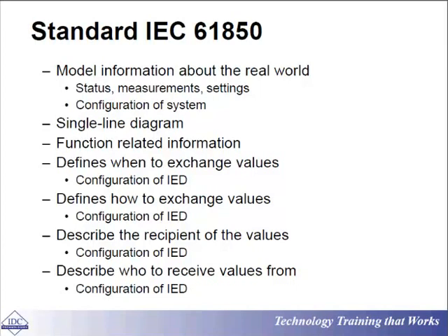So I'm just going to model the information. Model, what do you mean? Well, the status of what? Circuit breakers, for example, open, close, something, measurements. Measurements of what? Well, measurements of current, voltage, frequency, and things like that. Settings of what? Settings of the relays, for example. Configuration of the system, like what? Like, well, what kind of bus bar configuration do you have? Is that single bus, double bus, main and reserve, main and transfer, break and a half, or what?